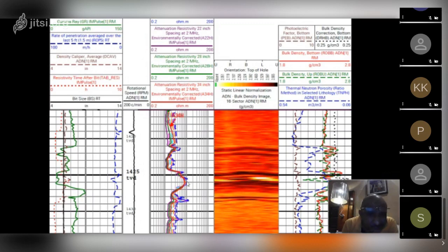Similarly, you will see at places this graph is also matching. Sometimes, because of the time lapse or something, the ROP shifts up and down. But you see this peak is matching this, so why? Let's assume this is oil. When there is oil, that means there is a porous formation. When the porous formation is there, we see a higher rate of penetration. This is gamma, but this is ROP.